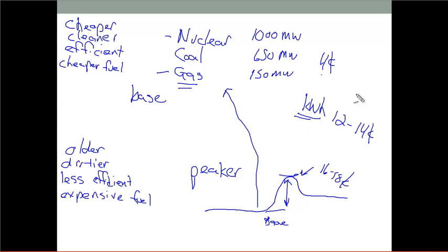So you've got to blend this out where you're able to buy the cheaper power, mix it in with a few hours of the expensive power, and then also maintain your grid. These are all the things that you've got to work out if you're running an electric company. But the main point I'm trying to make here is that these peaks in the afternoon, or in the morning, just depending on summer or winter, these peaks are always provided by more expensive power, right?